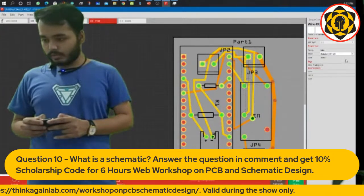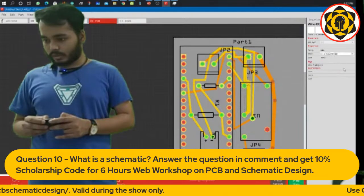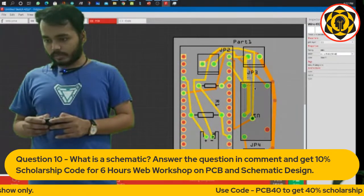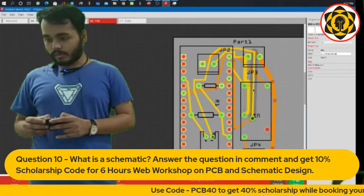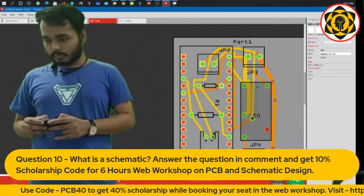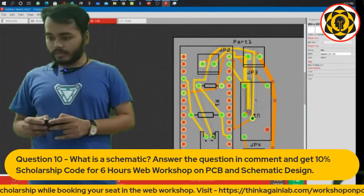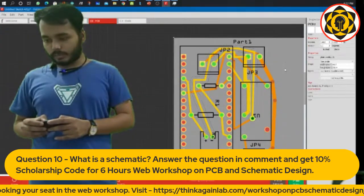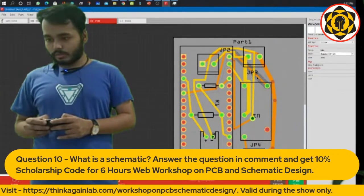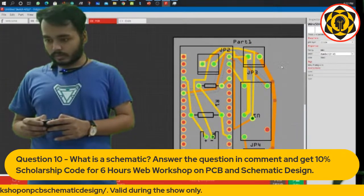This wire as well. It's slightly touching it there, but you cannot help it. I think I will auto route it once again. It's going to JP2. That's the connector. Okay, we can leave this one standard because the Arduino won't be consuming that much power. This wire also needs to be fixed up.